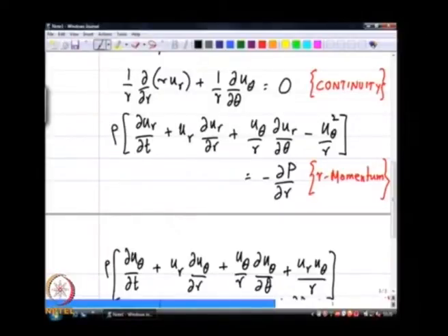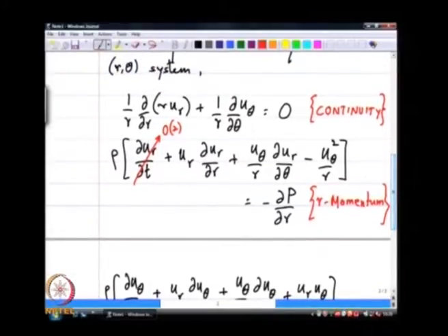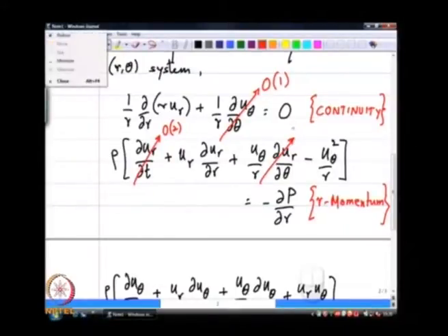So, if I now go through and scratch out terms and put in parentheses why that term is being scratched out, I will start with the first one. This is scratched out because of axis symmetry, this is scratched out because of the transient nature not being present.